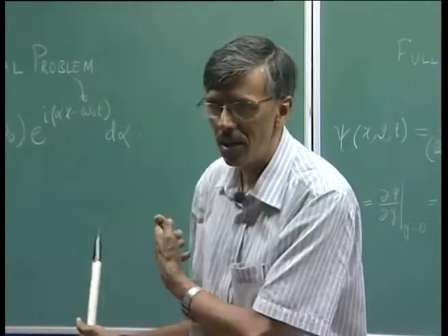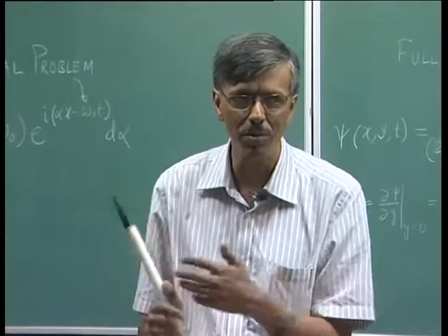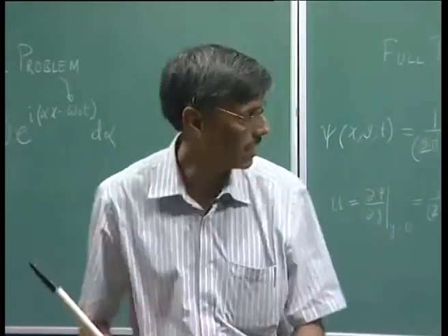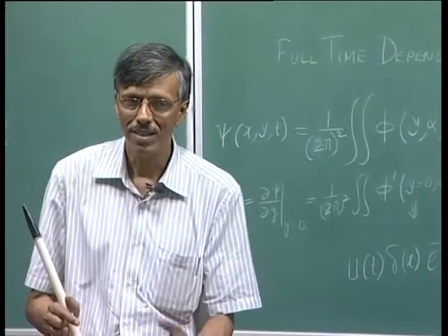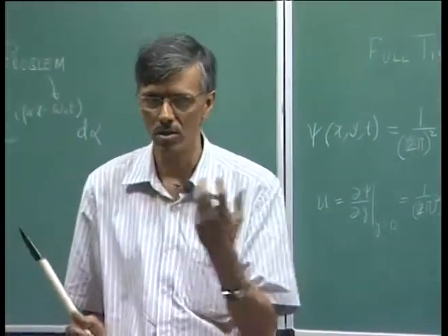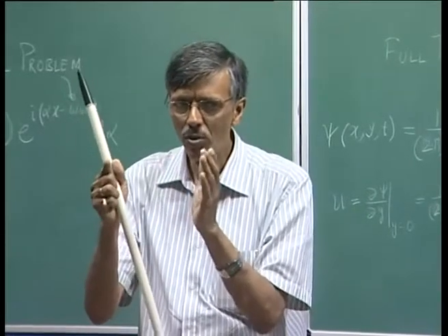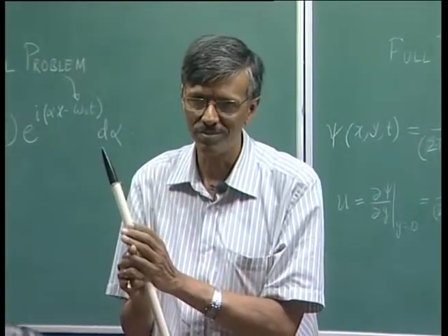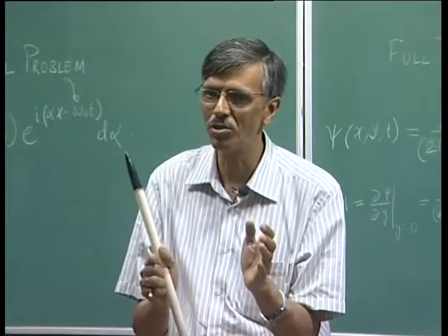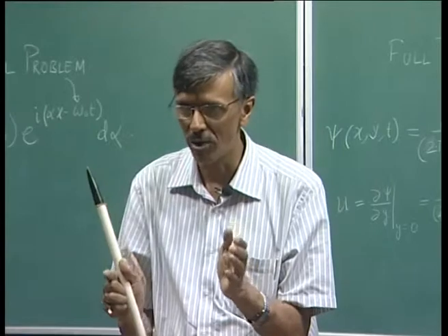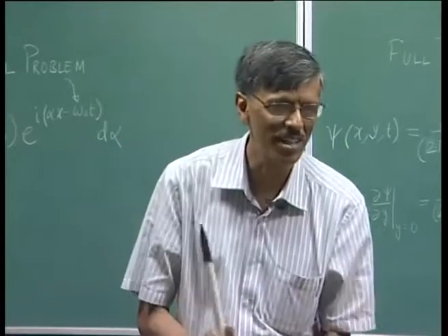The usual signal problem gives rise to Tollmien-Schlichting waves. But when we look at the full problem, we will see that ahead of this Tollmien-Schlichting wave, there is a very localized wave packet that moves. To give you an analogy, this spatiotemporal growing wavefront looks almost like a tsunami.